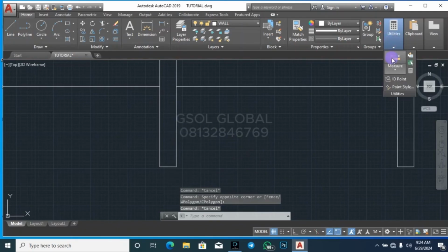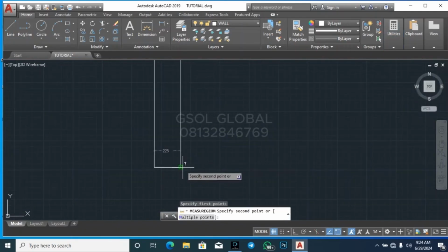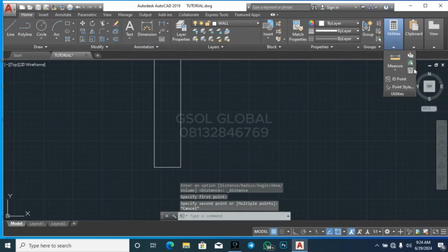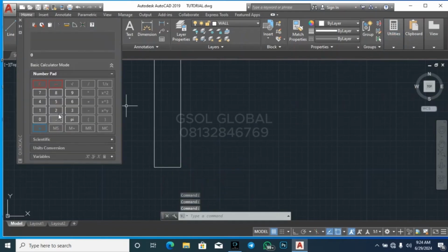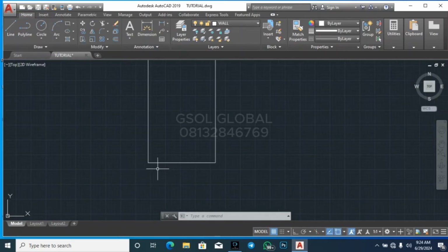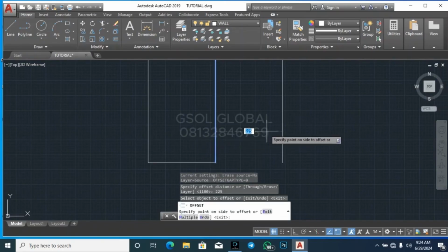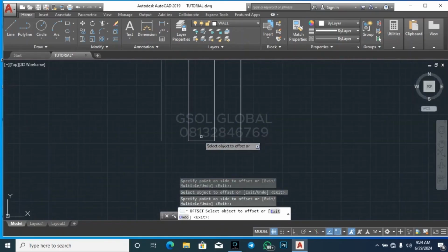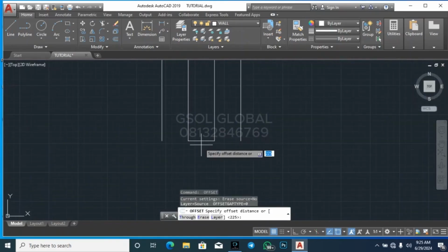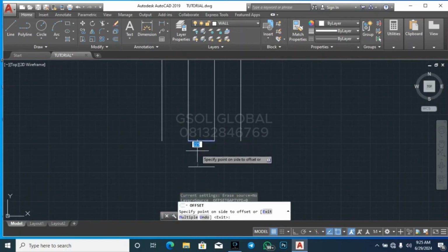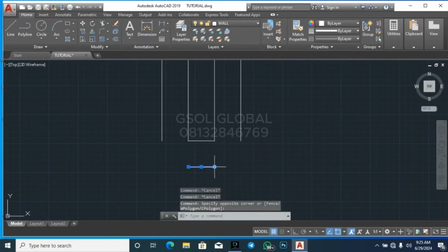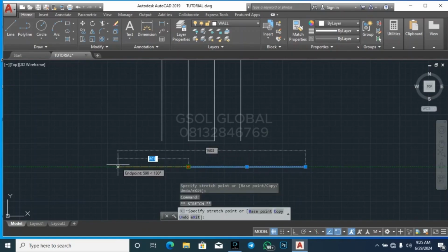So let's measure and let's see. So we're having what here? 225. So you go ahead and calculate. We have 3 times 225. What would that give us? 675, right? Now you're going to create a footing of 675. That's automatically 225 from both sides. So offset of 225 to both sides, you're having this here, and also offset of, let's say, 225 downwards. All right, so this is what you are going to be having, like this and like this.